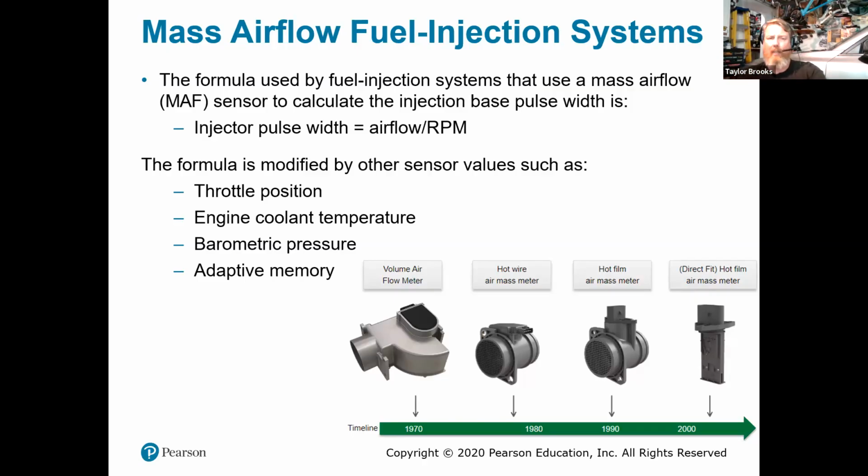So we're going to be taking an average of the ambient temperature and then using a hot wire system or a trapdoor system, like the very early system that I have photoed here on the left of the chart, which is basically a trapdoor system. Inside of that, it has a trapdoor that will move very easily against any type of airflow and operate off of that. So it's only going to have so much room that it can go in.